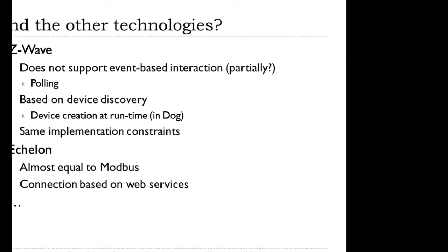We need to poll the devices, especially because battery-powered devices are not always available. So they come alive, you can query them, then they switch off for saving batteries, and then you cannot query them. So you have polling, but the polling depends on the state of the device. So might be you have 3 cycles of polling failing, 1 getting the data, and so on.